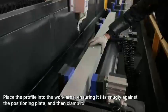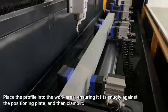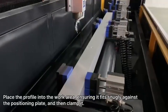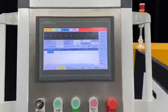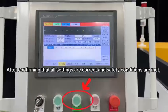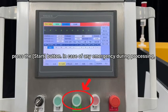Start processing process. Place the profile into the work area, ensuring it fits snugly against the positioning plate, and then clamp it. After confirming that all settings are correct and safety conditions are met, press the Start button.